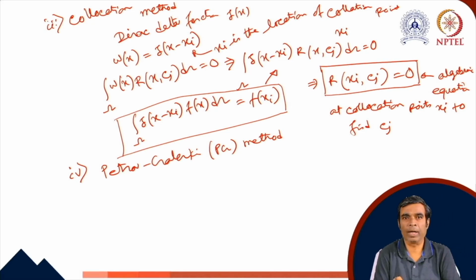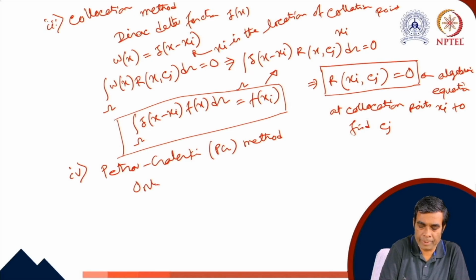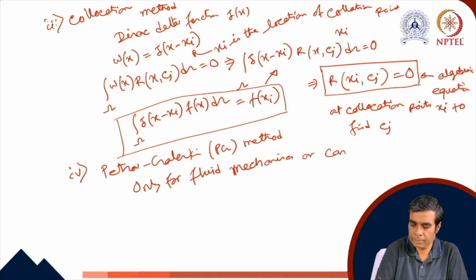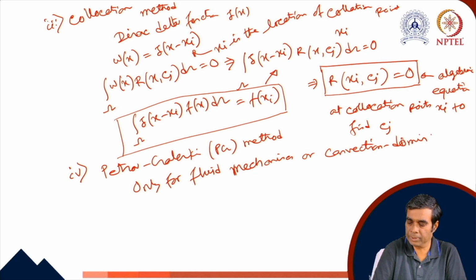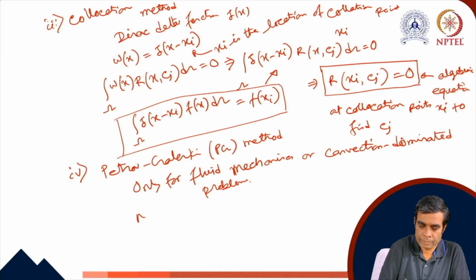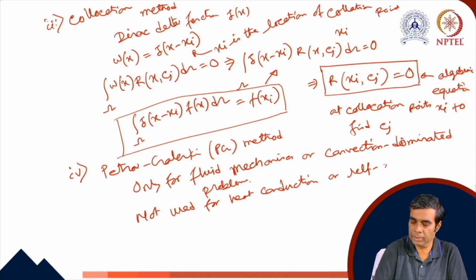This Petrov-Galerkin formulation is used only for fluid mechanics or convection dominated problems, not in solid mechanics problems, and not for heat conduction or self-adjoint problems.